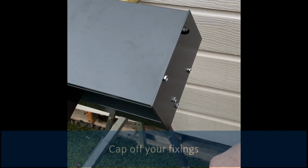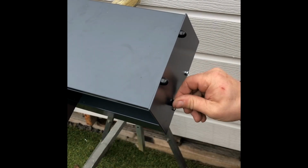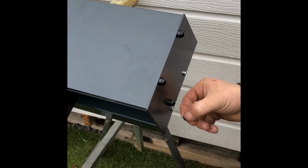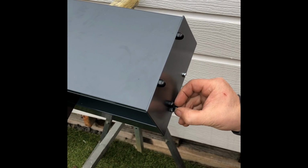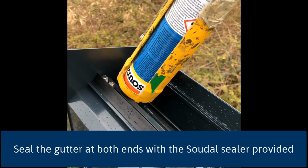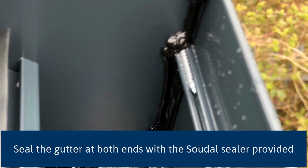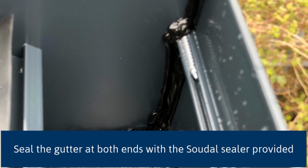Don't forget to cap off your fixings. Now, using the Soudal sealer provided, seal inside the end caps of your gutter section to prevent the water coming out of the ends.